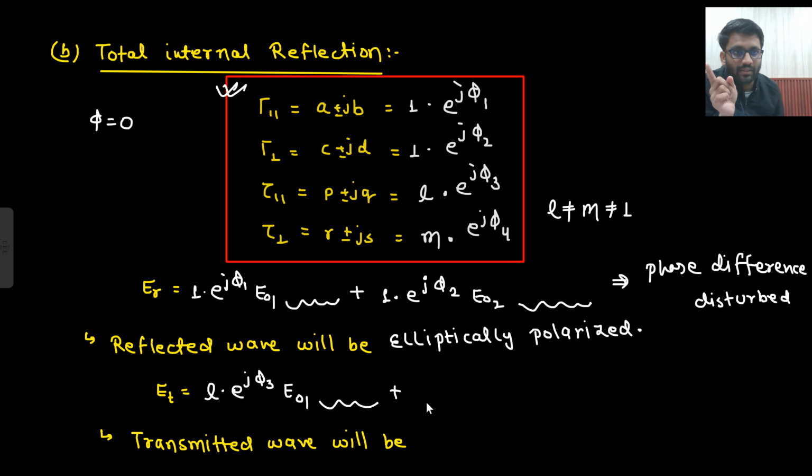In case of linear polarization, in case of circular polarization, I care about the magnitude as well. I care about the phases as well, and I care about the direction of propagation as well. Because if direction of propagation is different, then left circularly polarized and right circularly polarized, that case also will come into action. So that kind of question we will see as well.